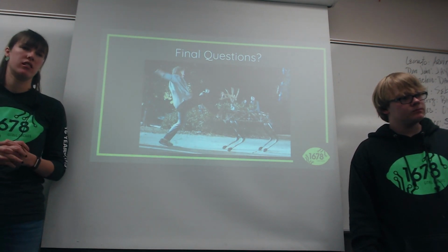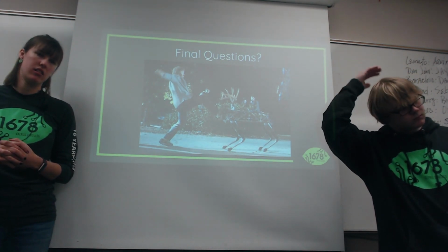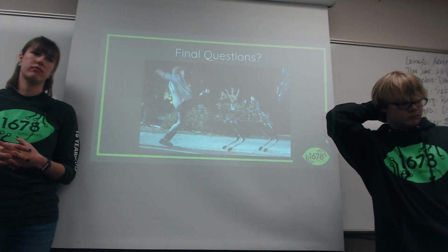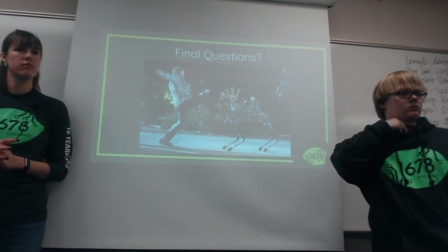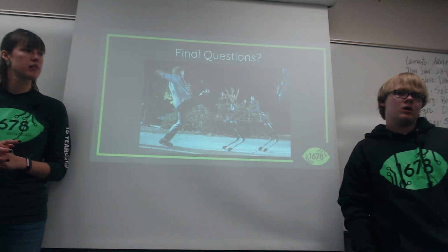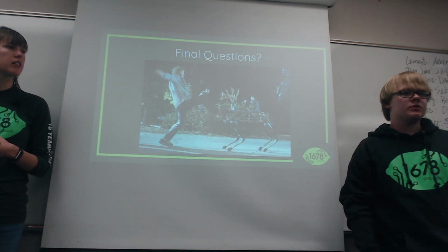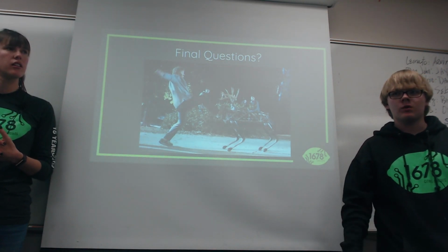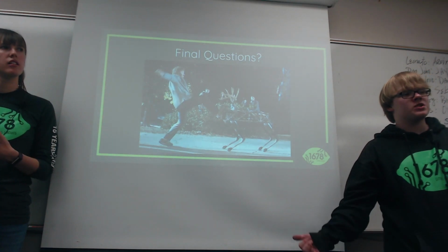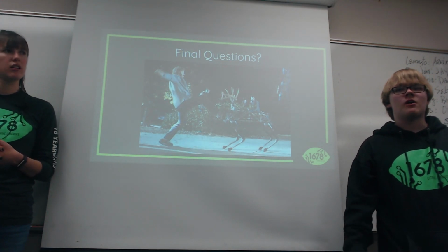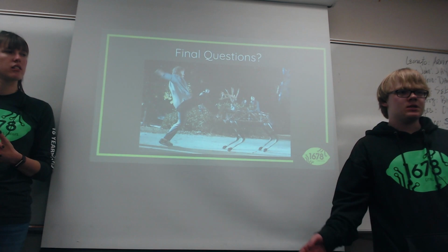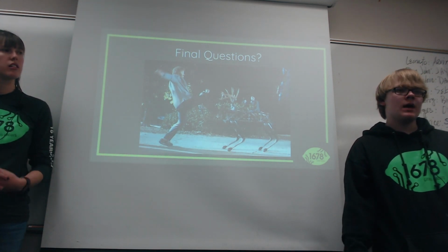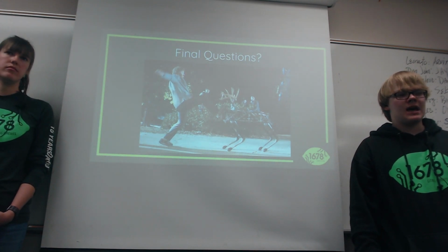I found your whole thing, you have the mechanisms separate from a software chassis. So you created the mechanism first and then you put it onto a chassis. Do you have a standardized chassis that you use? Not really. We generally try to use a 26 by 26 drive base, so that gives us a little consistency to work with. We find it small and it works really well with swerve. We have a standard alpha drive base that we use, so it's basically just a base swerve with one center tube. So for alpha, everything's designed for that, but following that, we don't really have any specifics.